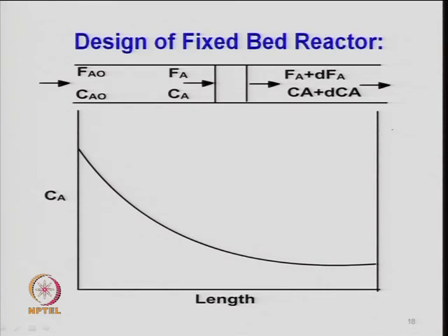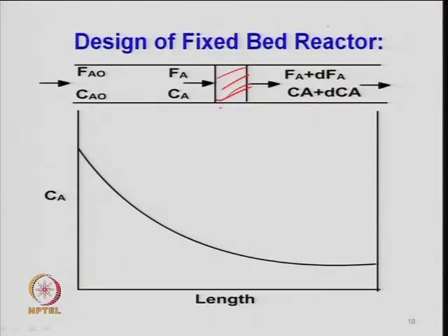I have already talked about this part, that you have a differential reactor when you look at the lab scale data. Generally the preferred one is the differential reactor, and I told you that theoretically the conversion should be less than 10%, that is the definition of a differential reactor. So, you should have a small diameter reactor with a small particle size and maintain the plug flow condition inside that, to neglect the axial and the radial dispersion. By selecting the reactor size, particle size, and a high velocity of the gas, that is F_A, one can control this.